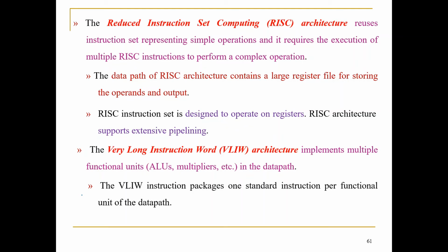Reduced instruction set architecture is all about, let me say that you have a CISC architecture here for a particular model, which is written using some 8-9 lines. Suppose you want to implement the same model using the RISC architecture, then this might go to somewhere around 10 to 20 lines, where every instruction is going to do a single operation, whereas here a single instruction was performing multiple operations. In the case of RISC, the time taken to execute one single instruction will be very less, whereas the memory required in order to store all these instructions is comparatively much more. That is what your RISC architecture is.